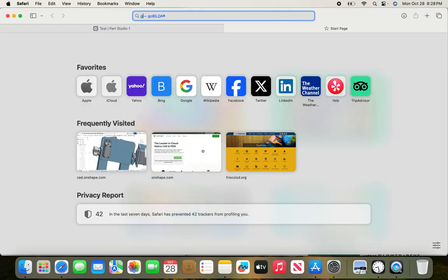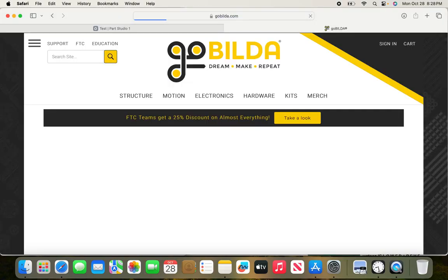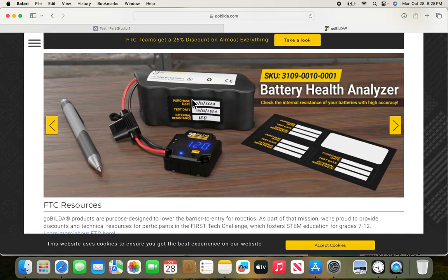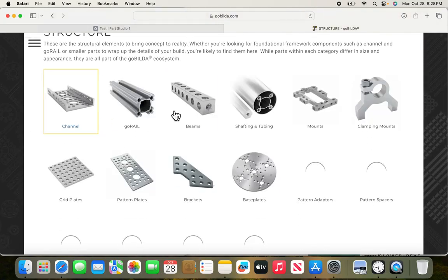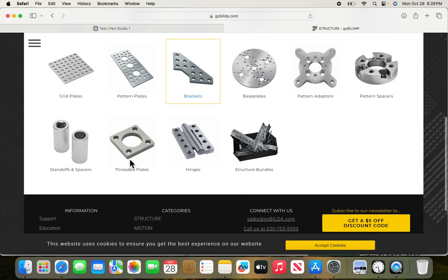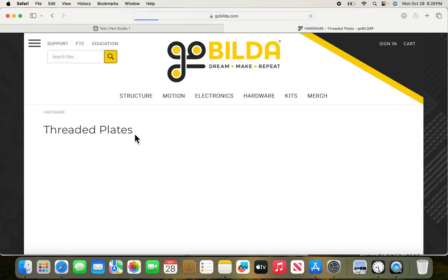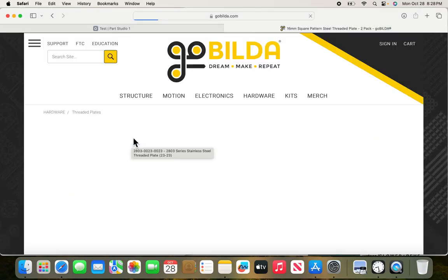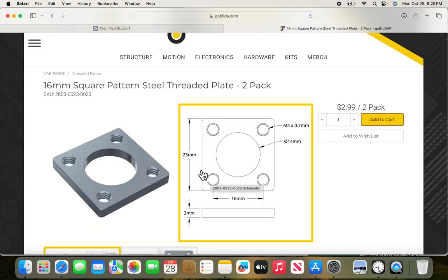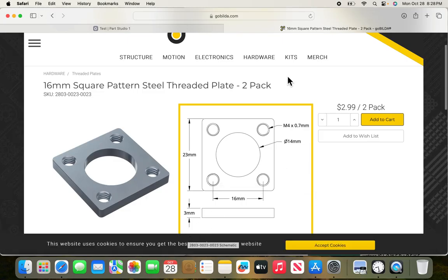The very first thing we want to do is see what we're actually trying to make, right? So there's this website that as a team we use. So we get metal parts, and I want to recreate one of these metal parts because it gets all the dimensionings. It helps. So I want to make a threaded plate on Onshape. Okay, perfect. So it's a 23 by 23 by 3 rectangle with some fillets, so some rounded edges, and with holes, right?